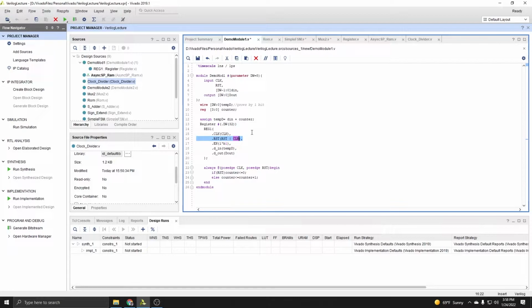that is a valuable tool that you can use to just, one, reduce the overall lines of code that you use, because you don't need to always have an additional line of code just for something as simple as an OR of two control signals that are driving a different control signal in a module. So just keep in mind that you're able to do that, as well as one other thing that the book never tells you that you can do.